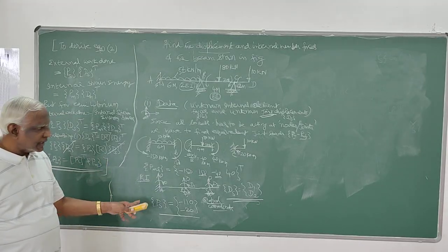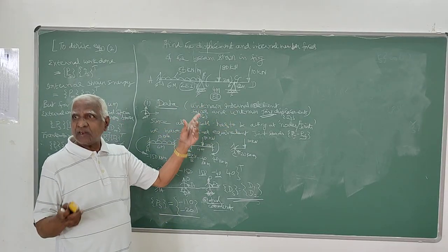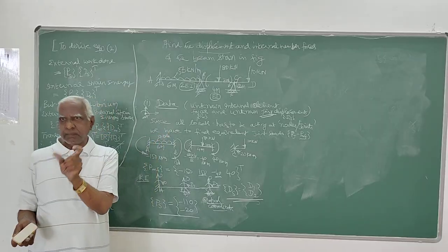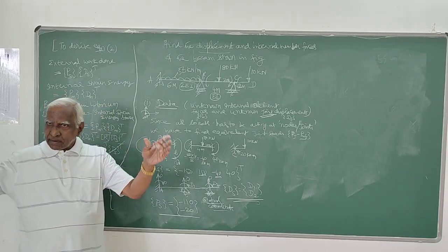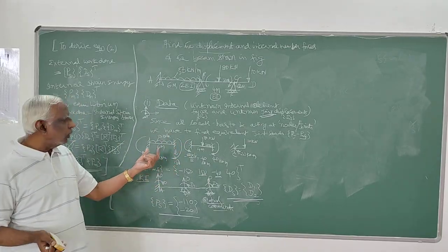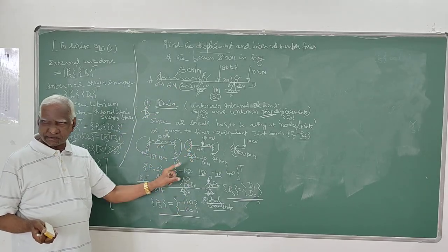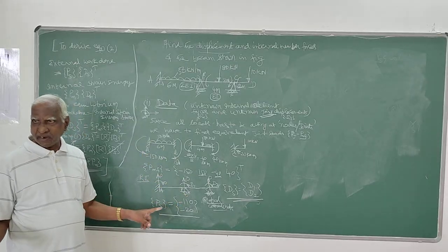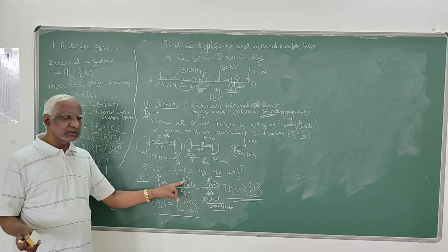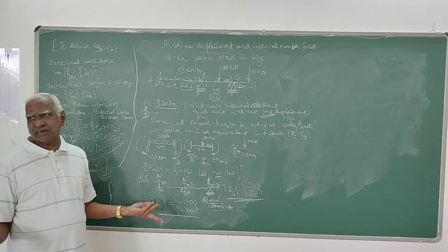And so next, local coordinates. We have to identify the member end forces. Which are the member end forces? In determining the stiffness matrix for a beam element, I told you the only independent end forces are the moments at the ends of the member. Though each member is subjected to a vertical shear at the ends and the moments, the independent forces you can select are the moments at the two ends. Once you solve the moments at the two ends, the shear you can determine by equations of statics.